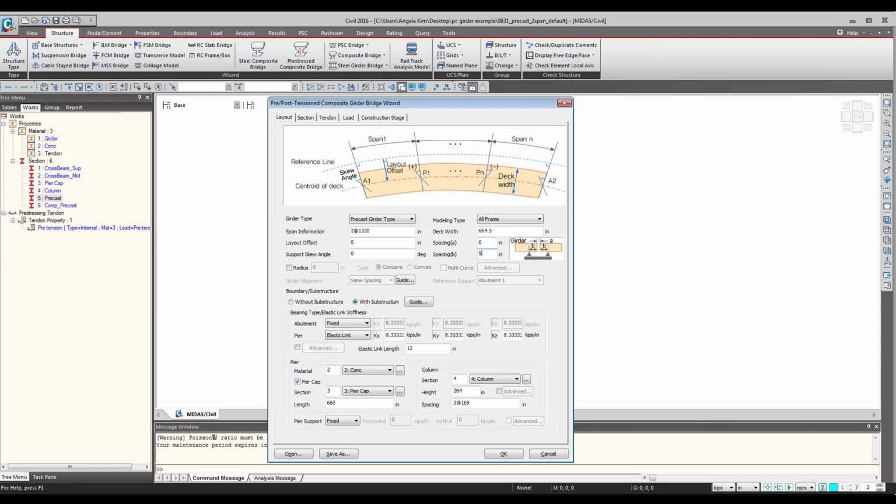It's a detail, but some programs are not able to handle this. Also for clarification, I had a few notes. The section and material properties are not saved in the wizard file, but they are saved in the base model of Midas Civil, with the extension MCB.